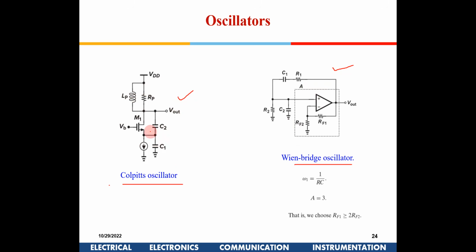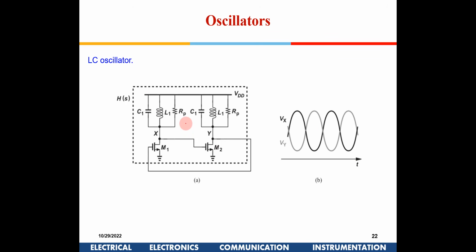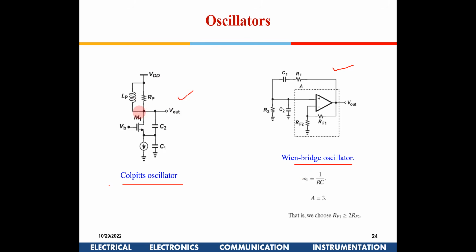If you see here, these are all small oscillators as compared to all these other oscillators. So this is a single MOSFET amplifier oscillator, just single. So how this phase shift is done out here. You see there is no input signal for all these things. Okay, they will start oscillating. So just try to see the derivations for these things. Okay, this RF1 and RF2 have been given to adjust the gain of this amplifier.